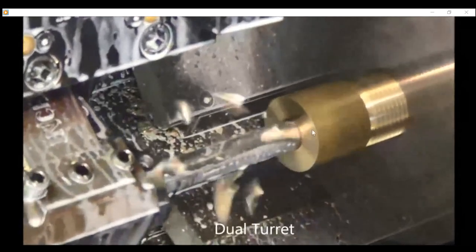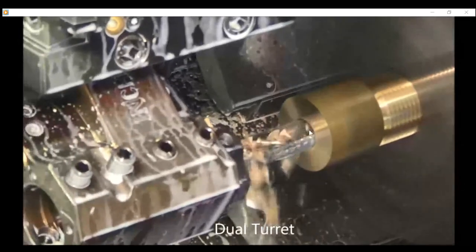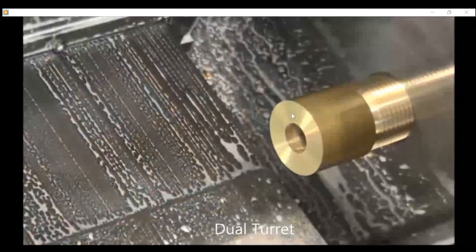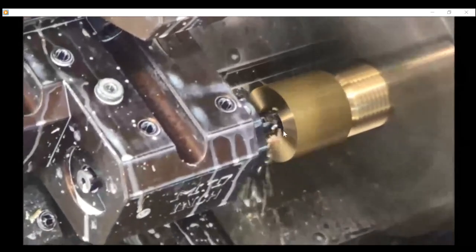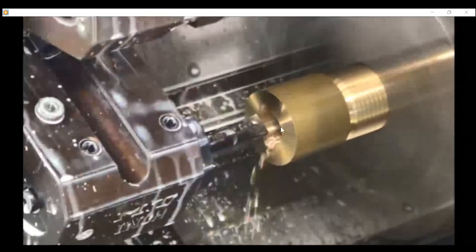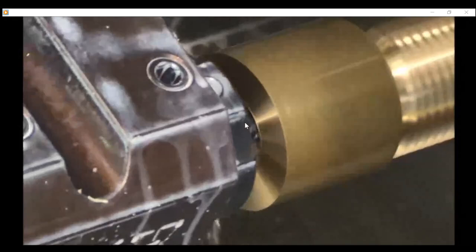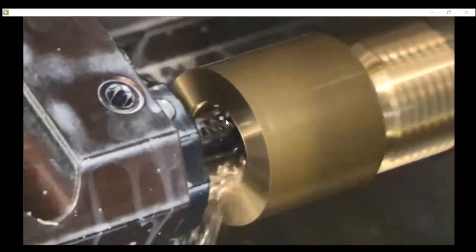Here we drill, we create the hole. On the other side, we remove the material, we create the hole. Then the hole will be extended now. And then now, this is the internal turning. Can you see that internally? So first we must drill. We must create a hole. Second, this is the internal turning. The tool, you can see that inside, is enlarging the inside.